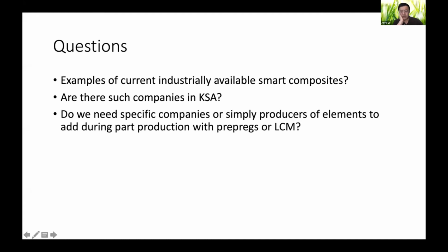Even the currently 3D printed carbon fiber, the failing rate is actually relatively low compared to the commercial ones. I think Markforged, that's the company making these carbon fiber filled composites. It's kind of nylon based. I think their failing rate is 30%. There are several companies now making long fiber reinforced 3D printing, but they all have the problem of consolidation.